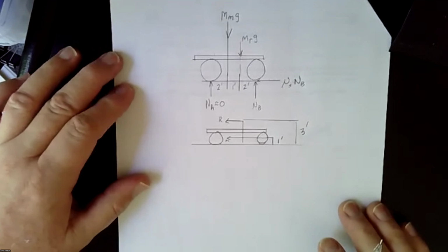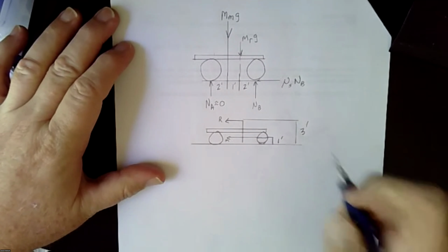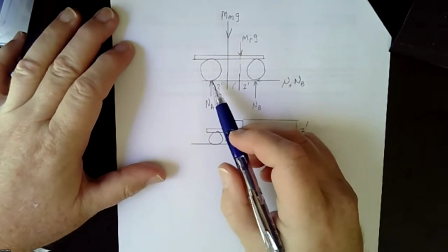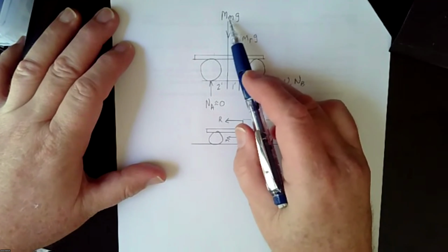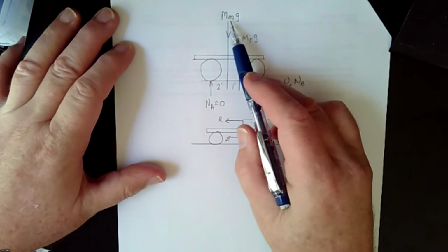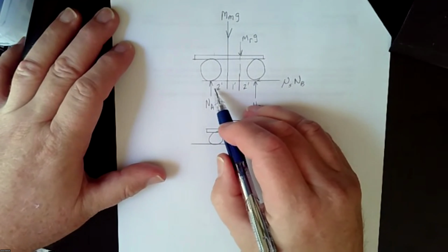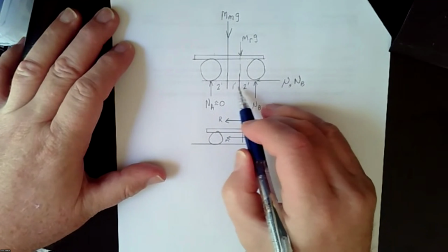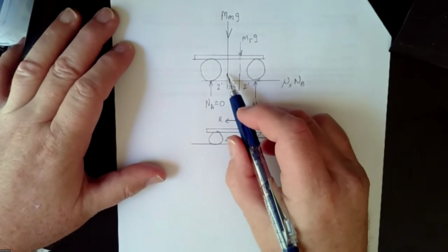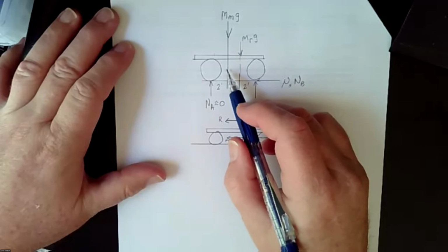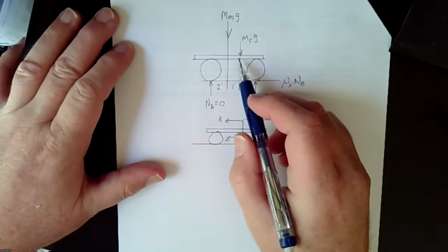Okay, here's my drawing. Now it might help to have the picture that I posted next to it. So I have the wheels, normal force A, normal force B, friction, mass of the motorcycle. It's not really a motorcycle, but I just use M, and then mass of the rider. So that's where their locations are. So the distances that are important are 2 feet, 1 foot, 2 feet. So the 2 foot represents where the center of gravity of the ATV is, and the 1 foot up here is where the center of gravity is at.